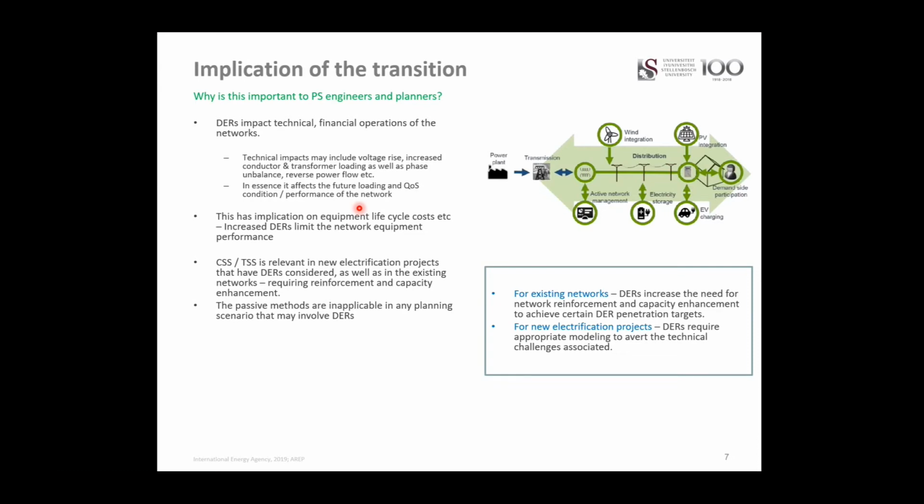may involve DERs, just based on the fact that they were not built for distributed generation or to handle an active distribution network-based kind of operation. So in summary, I can say that for existing networks, DERs increase the need for network reinforcement and capacity enhancement, where the planner wants to achieve a certain DER penetration target.